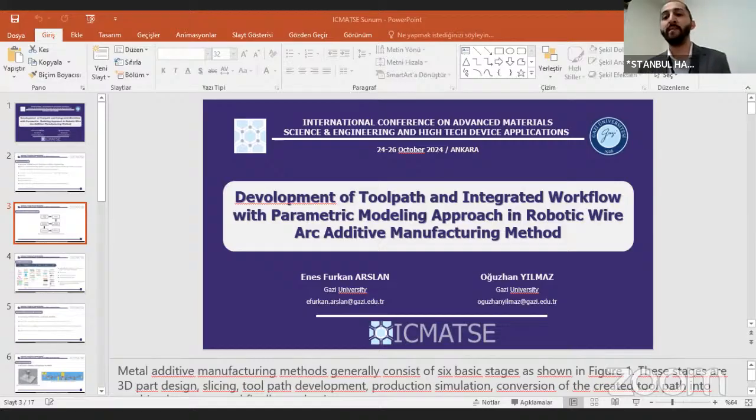Subsequent to parametric model creation, a slicing strategy was developed as an alternative to existing slicing software. A strategy grounded in the direct slicing of the NURBS model within Grasshopper was devised. This strategy enhanced both the dimensional accuracy of the part resulting from the deposition process and the performance of the robotic production. Figure 5 presents the algorithm developed for the slicing strategy.